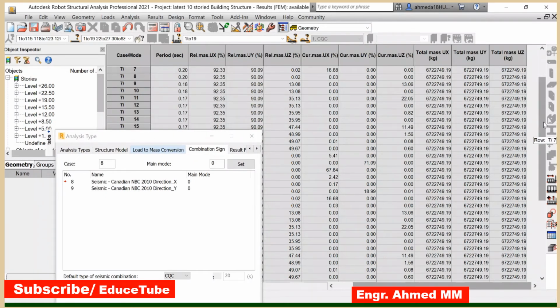Let's see here. I'll click on top, then we can see the dominant mode is number 3. Here you can see this is 67.64. This is the dominant mode, number 3. This is for X, so direction X. Click here, put 3, then set it. It will change the mode number; instead of 0 it will be 3 now.